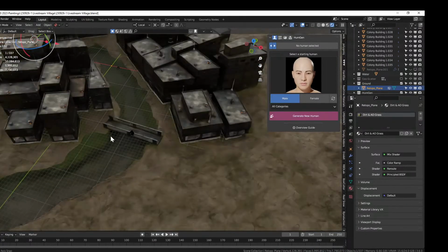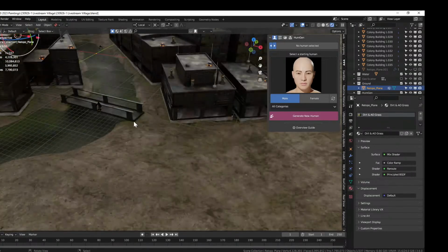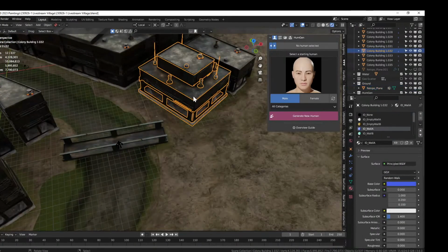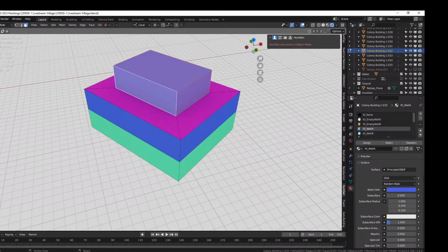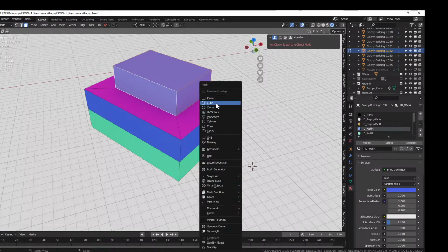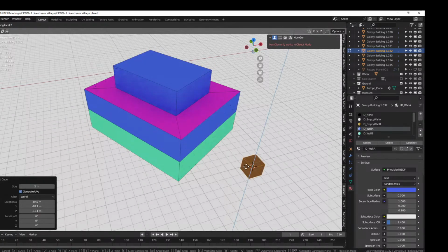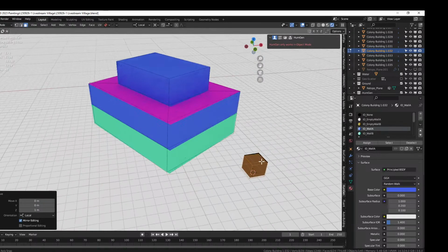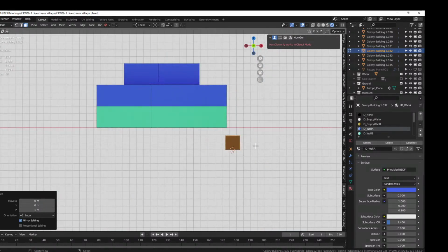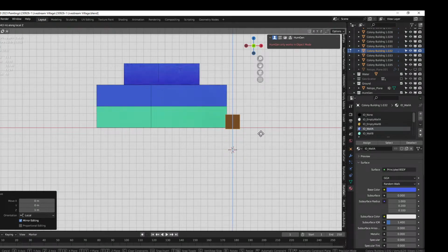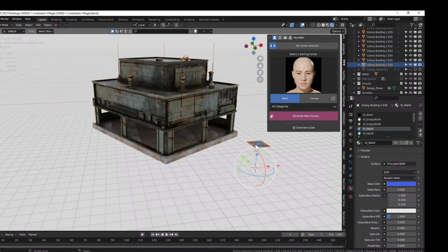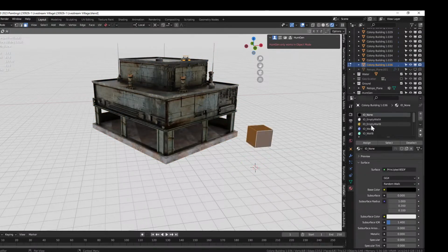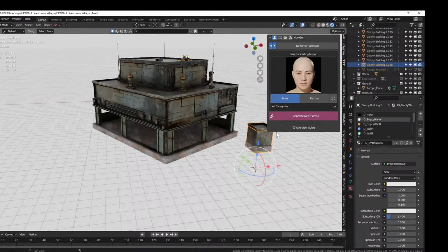Let's build one more building from scratch, just sort of for the fun of it. Let's solo this building here. We'll use it as our starting point. And edit. And over here, Shift A, Mesh Cube, GZ 1, and even maybe more. GZ up to there. Okay. Now P by selection, tab, this one, tab, A, empty walls A, assign.